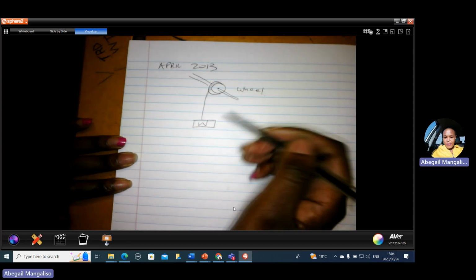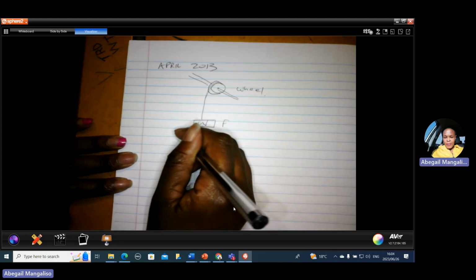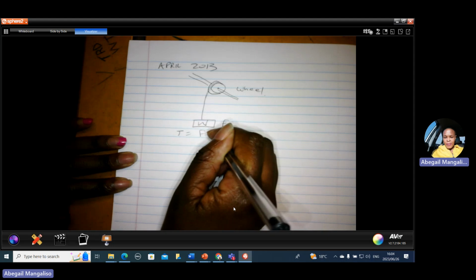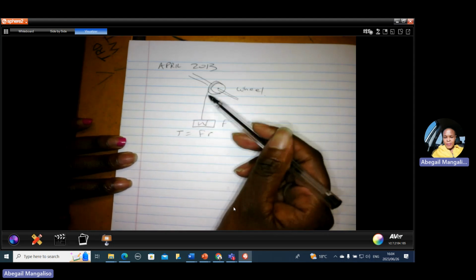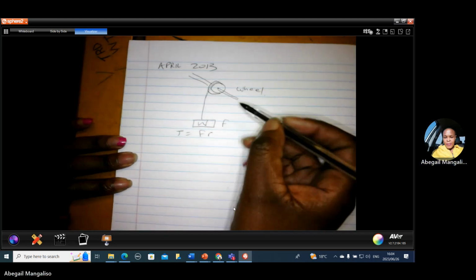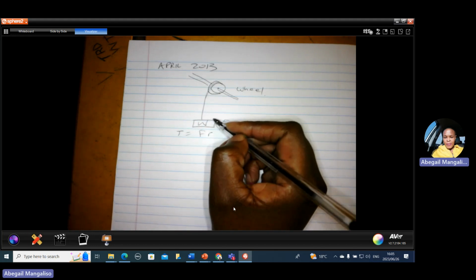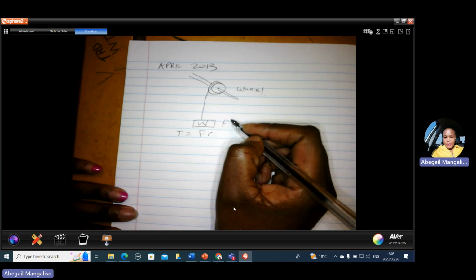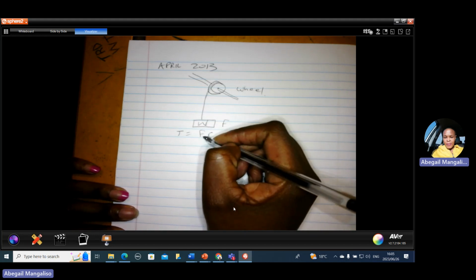So this load will be the force that you use to calculate torque, where torque is equal to F times R. This is the force exerted on the circumference of the drum or the wheel. If it's given in kilograms or tons, you convert to kg and multiply by 9,8 to get a Newton.